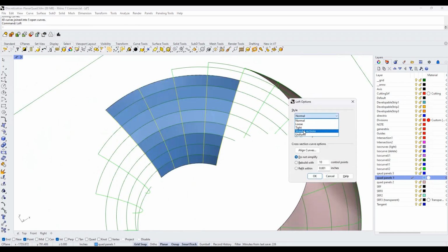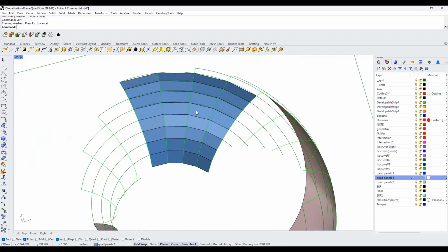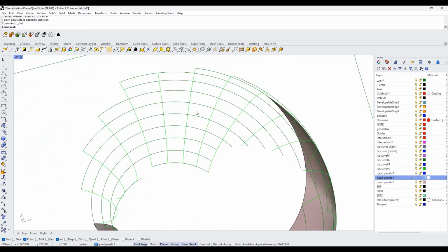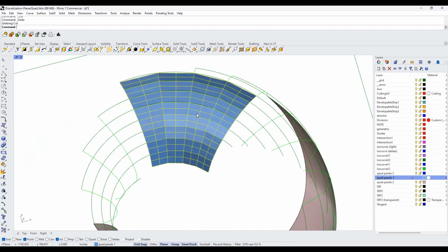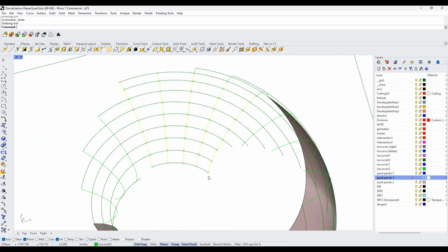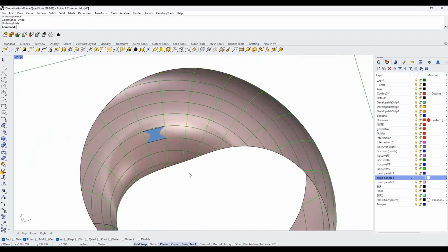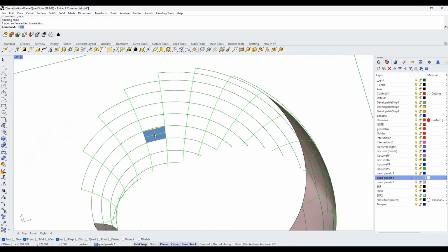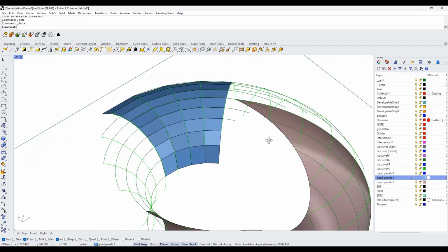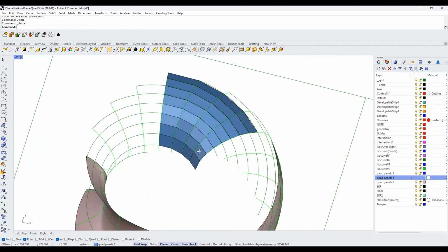You have to use the straight sections command and hit OK. Then you can copy this, cut it with Control X, and then undo all the way back before you did that damage to your underlying model, and then you can paste it. So that's a faster way.